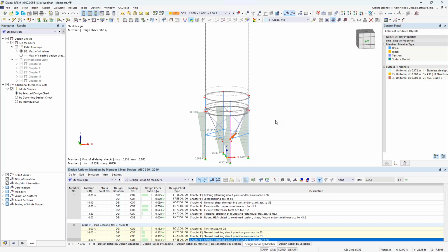So when we are performing a general static analysis, buckling is not necessarily considered. Now, if you're running a second order or a large deformation analysis, the program will give you an instability if you exceed the critical buckling load of either a surface or a member. But it's just a general instability without much more information. So how can we take structures such as this to evaluate buckling considerations?